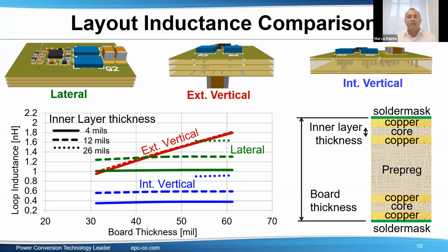It is clear that as the first inner layer moves further from the power loop, its effect is an ever increasing inductance, given the current mirror effect diminishes with distance. That's the reason why you see the green curve increasing.